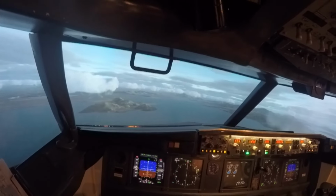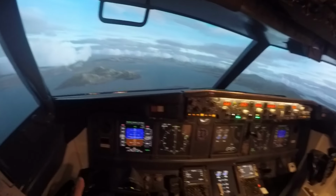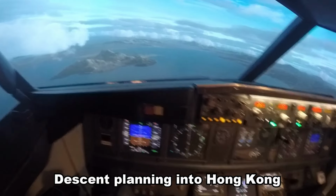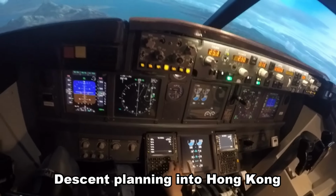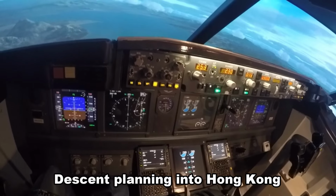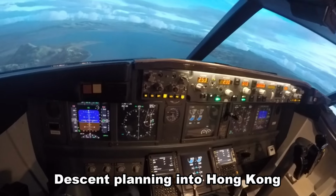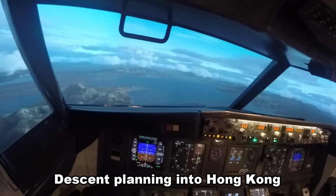So we'll start planning our descent into Hong Kong Chek Lap Kok International Airport. So we'll just program our CDU. So we'll be landing on runway 25 right on an ILS approach. So we'll be landing with flaps 30. Our approach speed will be 135 plus 5 knots, which makes it 140 at flaps 30. We have a course of 253 and an ILS frequency of 110.9, which we have already inputted,